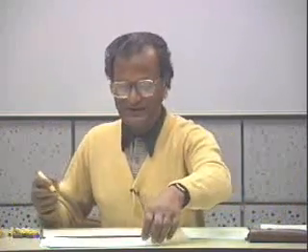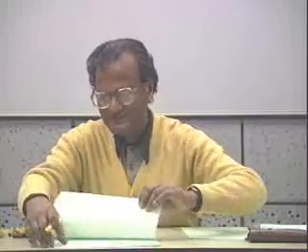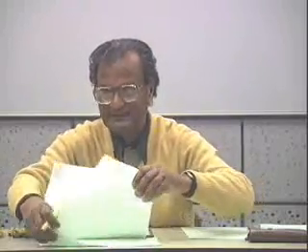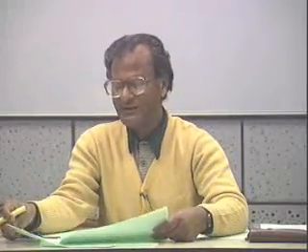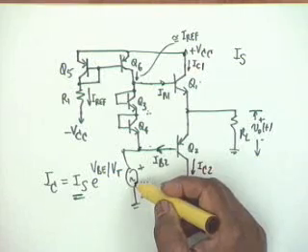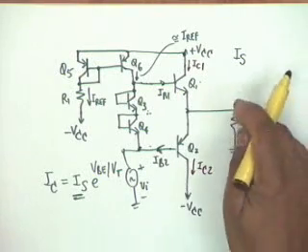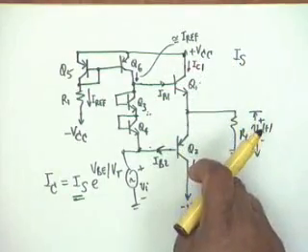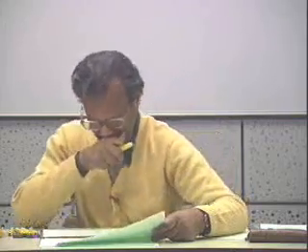as far as the transfer characteristic is concerned, let me go back to this circuit. Have we assumed that there is no current flowing through RL? We are considering the DC conditions, therefore Vi equal to 0 should give V0 equal to 0, and therefore no current. Is that clear? Once we assume IC1 equal to IC2, these are DC conditions. There is no signal applied. If Vi equal to 0, then V0 should be equal to 0, and therefore no current flows through this. So current must flow like this. Agreed. But I brought out this figure for a different reason.